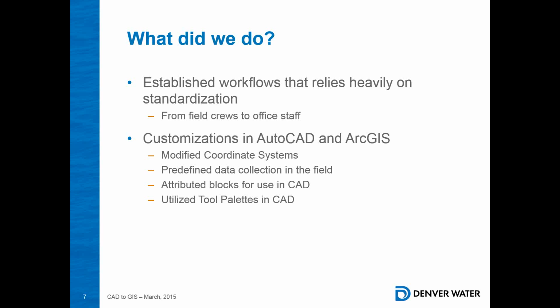Well, kind of just to describe our tool palette, what we did is anything that we wanted to push to our asset recording group for posting purposes, we've created a CAD to GIS tool palette within all of our Autodesk software. So right now we're using Civil 3D and Map 3D. We have these tool palettes in there, and the tool palettes contain customized tools for creating line and polygon features that will put them on ARG prefix layers automatically.